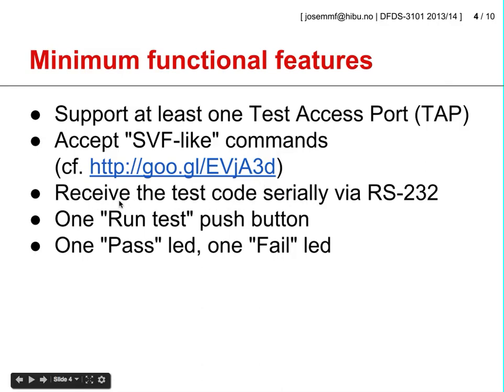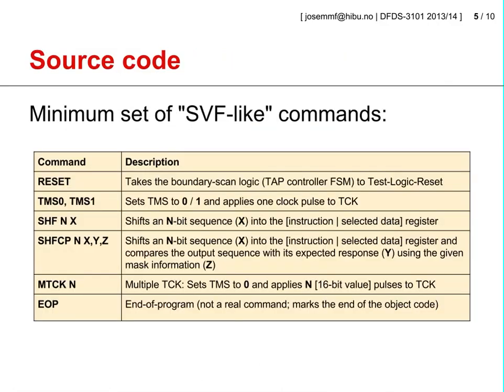So our system shall be able to receive the test code serially using an RS-232 port, and it should support one push button for running the test and two LEDs to indicate the test result, either pass or fail.